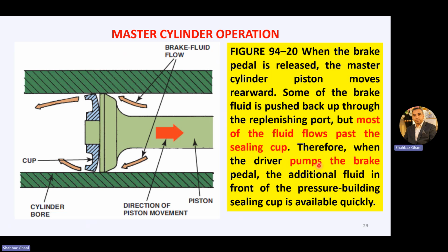Therefore, when the driver pumps the brake pedal, the additional fluid in front of the pressure-building sealing cup is available quickly. So some of the fluid goes back to the replenishing port and most of the fluid goes past the sealing cup here, so the replenishing fluid is readily available. It will help you quickly build up the pressure here.